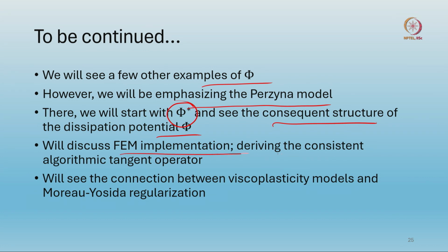Then we will be discussing the FEM implementation for this in full detail. Basically, we will be deriving the consistent algorithmic tangent operator, which goes into the construction of the modified stiffness information in finite element implementation of this plasticity, okay. Also, we will be seeing the connections in future between viscoplasticity models and the famous Moreau-Yosida regularization. All of these are coming up, so there are very interesting things afoot.